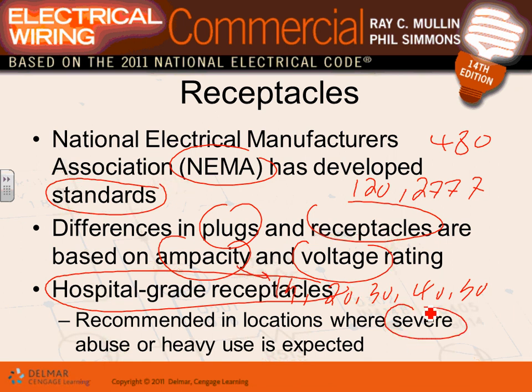So that's it. In the commercial project, Derek, my friend, we will be using what we call spec type receptacles. All the engineering firms, when you look at the specification that we have, they talk about spec type receptacles. A spec type receptacle is a commercial grade receptacle, not the residential.